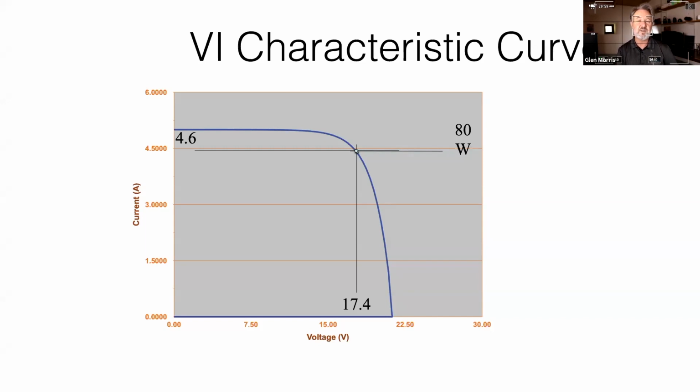Old ones didn't used to do this. They used to just have a simple current limiting feature, but modern ones can actually track and adjust the input-output voltage. And solar inverters that connect to an AC output have to do this to operate over a range of power conditions. So what we'll see is the inverter will try and find that sweet spot on that curve by adjusting its input impedance and therefore adjusting the amount of current it draws and therefore modifying the voltage of the array until it sees the maximum power. Now this is not a static position. That point moves all the time.